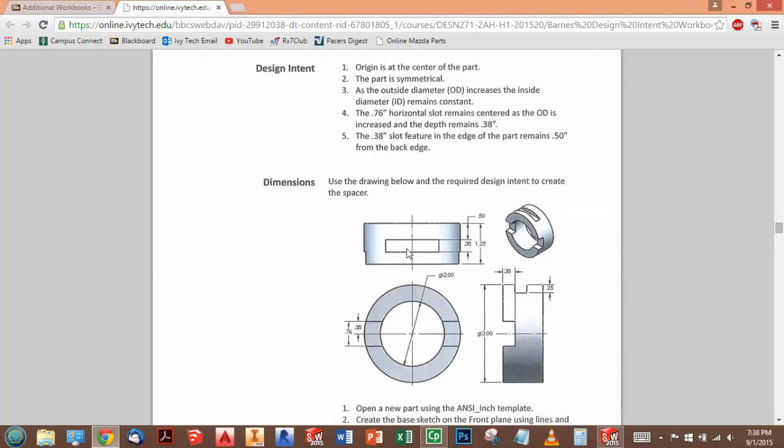And if I go to a Control 8, so I'm looking right at the end of this, going back to our problem here, we're going to sketch out a rectangle right here basically, and we're going to cut that down into the model. And we have our dimensions right here. So we know it's going to be 0.25 deep when we actually extrude it or do the extruded cut. And it's 0.38 tall, and they haven't given us a depth dimension or a width dimension, so we're going to say that's 1.75 since they haven't really told us.